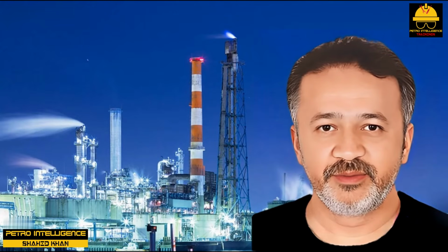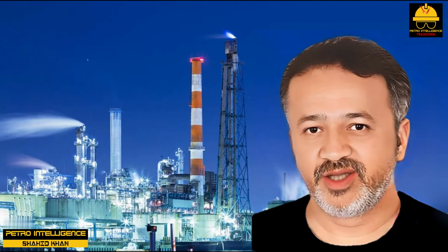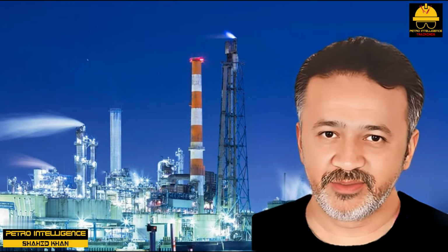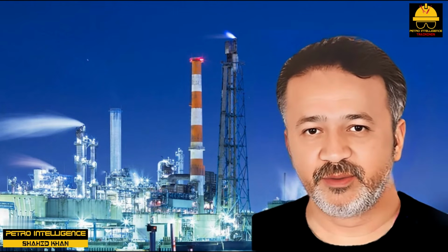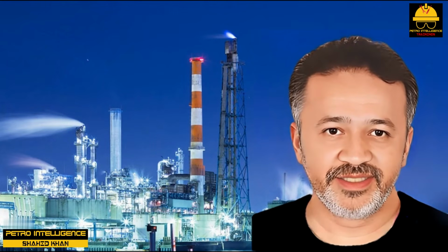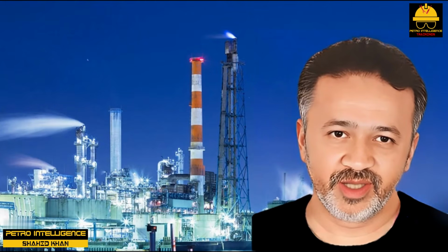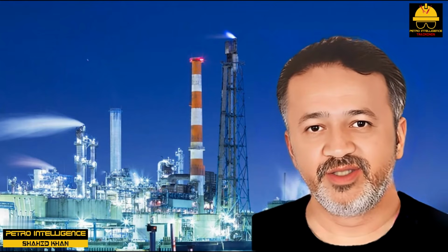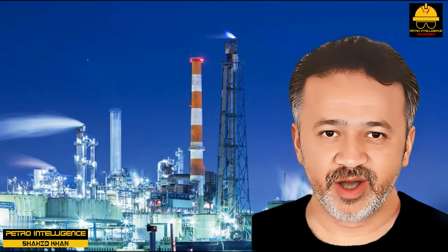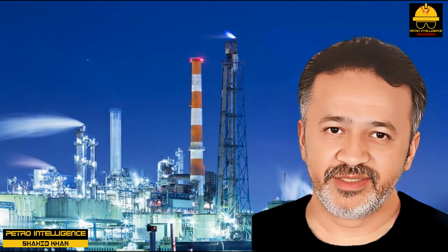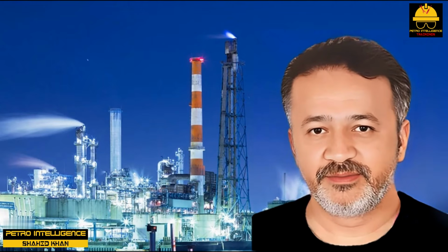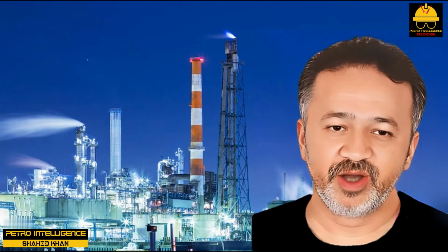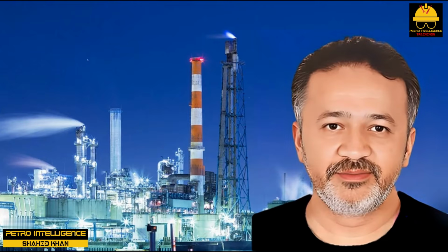Spillback. Spillback bypasses the compressor discharge gas back to the compressor suction. This is a relatively energy inefficient way to increase the evaporator temperature. Spillback is discussed in another lecture on centrifugal compressors and surge. Discharge throttling. Discharge throttling is also an energy inefficient way to control the evaporator temperature. Even worse, if we are working with a centrifugal compressor, discharge throttling may cause the compressor to surge.